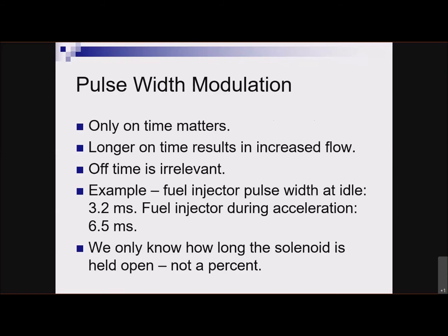Fuel injector, to deliver more fuel, we lengthen the pulses. Do we care how long the thing stays closed? We do not. That's immaterial. We only care the length of that pulse. And when I say length, I mean time, duration.